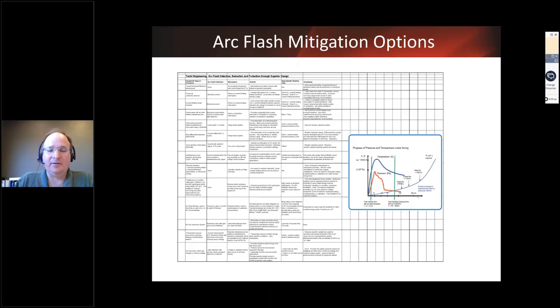Although we're passionate proselytizers of arc quenching, which sits at the top of the pyramid, so to speak, in terms of arc flash mitigation effectiveness, we regularly implement zone selective interlocking, differential relaying, and other methods in this chart. It is our opinion that the only method in this chart that we do not actively support, and in fact will only implement upon written customer request, are maintenance switches.